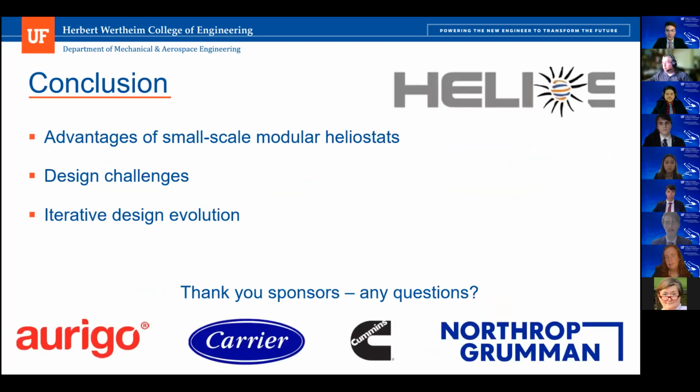Finally, I'd like to address the advantages of a small-scale heliostat. Smaller modules increase the overall optical performance of the heliostat field by increasing the accuracy per module, thus generating a higher concentration ratio at the receiver.